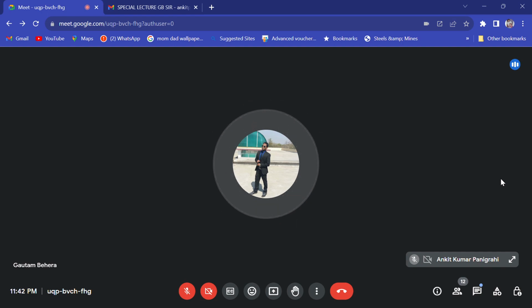But when we are doing top blowing, we are doing water cooling always. We are protecting our nozzle by doing water cooling. So that is called a water cooled lance. That's why the lance tip is made of copper, because copper has high thermal conductivity. It can lose heat easily, and it is water cooled copper, right?